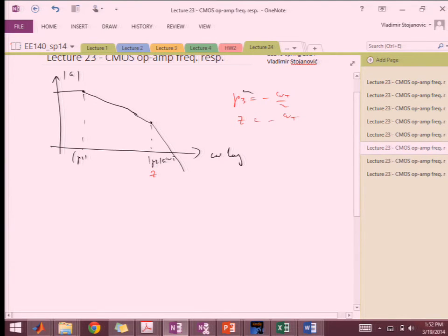And then you have your new pole kind of half shifted down by 2x. So this is your pole 3, right? So if you draw the new phase margin, it essentially drops here by 90, and then around pole 3 drops by 90, rather than extending over here and then dropping here by 90, right?